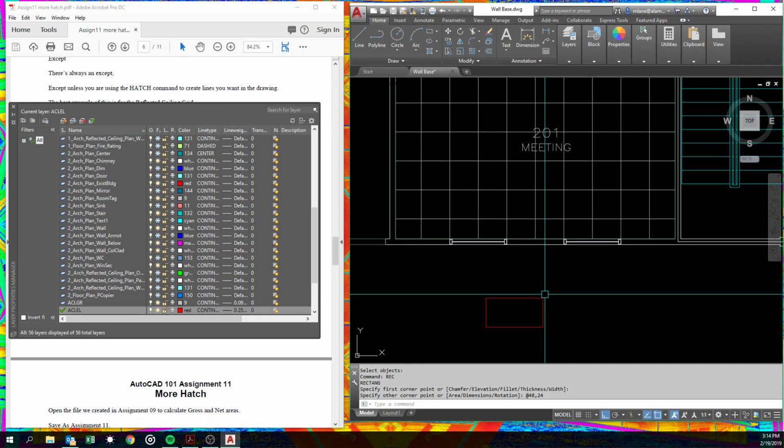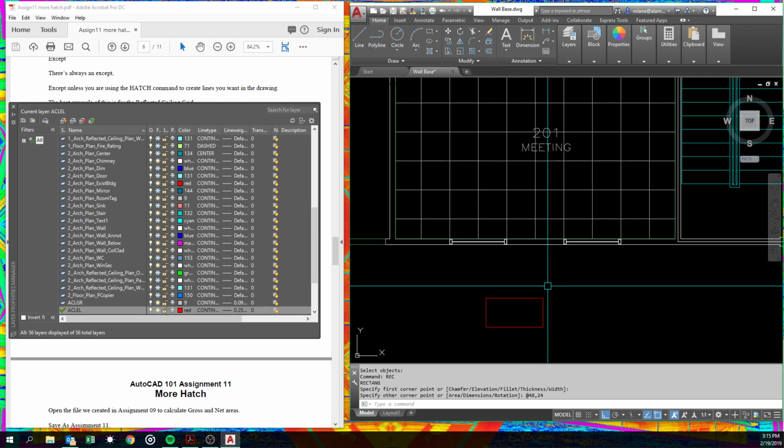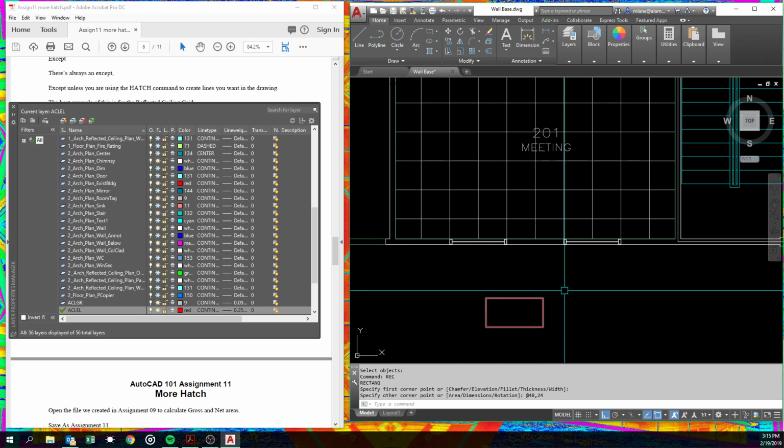So the drawing itself has a 0 point, a 0, 0 up, 0 over. And what that F12 does is, if that's not set, that's dynamic and coordinate entry. Coordinate entry sends you to that point that's 48 inches over and 24 inches up from the 0, 0 point. We never need to worry about that, so you probably always want to have your F12 dynamic on. If you're talking to old CAD monkeys like me, we don't. That's old, and so we have to put an at in front of everything. Real annoying. Anyway, don't worry about that.